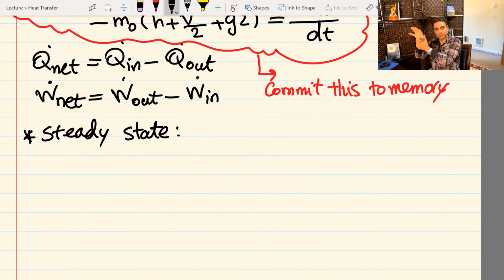If you follow that mass of steam that was high pressure and went into the turbine and came out of the other side with low pressure, that system, which was 1 kilogram of the steam that I followed, that was my system. That is not a steady state case. Not at all. You have to apply the unsteady form of the first law to that one.